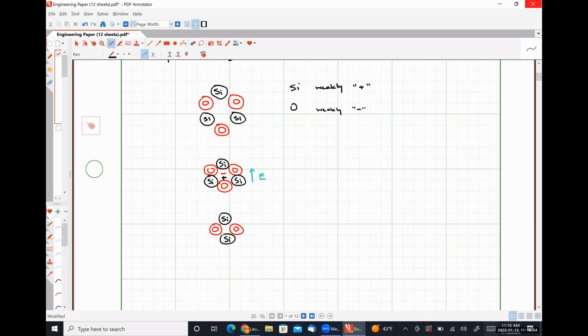Most digital watches, I say most, it's really all digital watches, use what's called a quartz crystal resonator that resonates at a very specific frequency. Let's call it 32 kilohertz, but it's not really 32 kilohertz. It's whatever 2 to the however many powers gets to the ballpark of 32,000 it is. And it's mechanically tuned, so the crystal is trimmed to have that particular resonant frequency, and it uses that exact number of oscillations per second to tell your watch how long a second is, right?